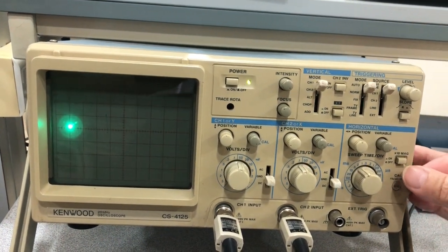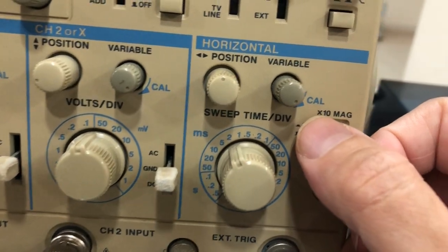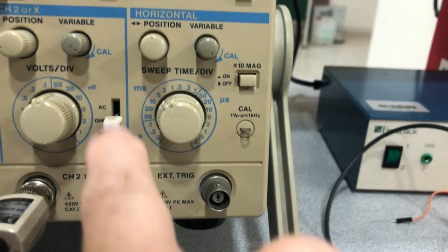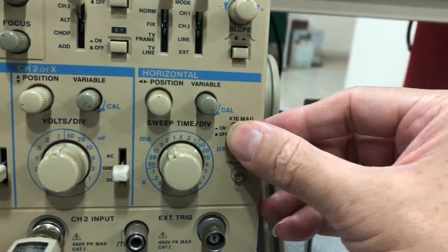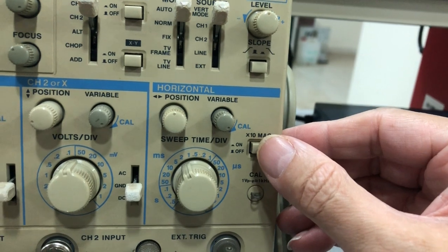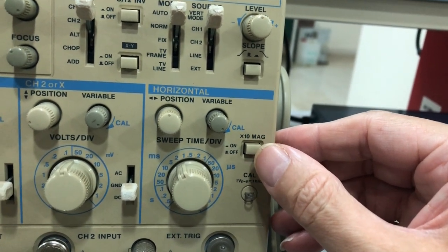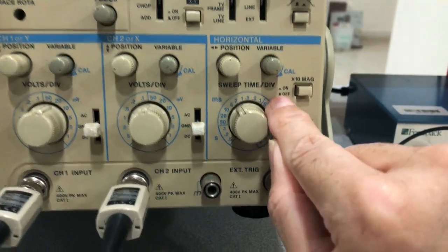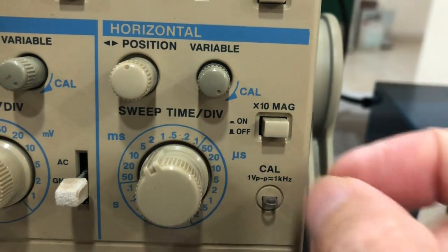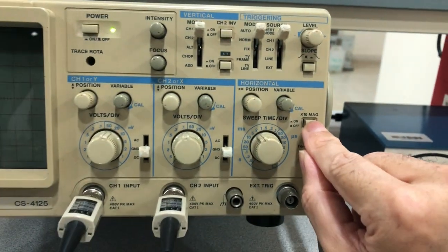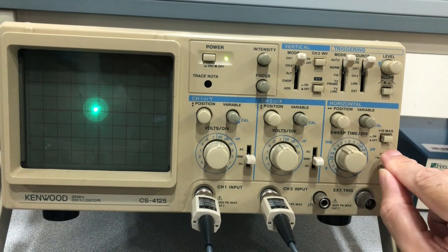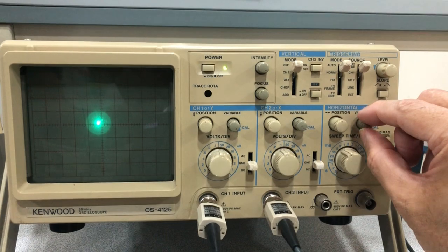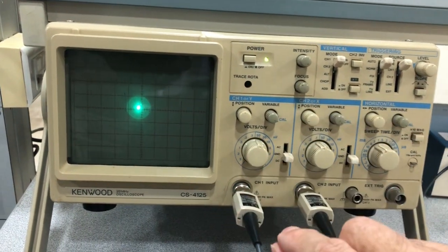Now, I turned off, let's learn this button here. It says times 10 magnification in the horizontal way, because this is the horizontal control, meaning time control. So I don't want to use the times 10 unless I need to zoom into a signal and look at it in time, zoomed in. It says here pushed in, on. Pushed out, you see here it's longer, the depth of the switch is taken to the outside, so it's pushed out. So I took the times 10 magnification in the time axis off, okay? Now, I still don't see a horizontal line.